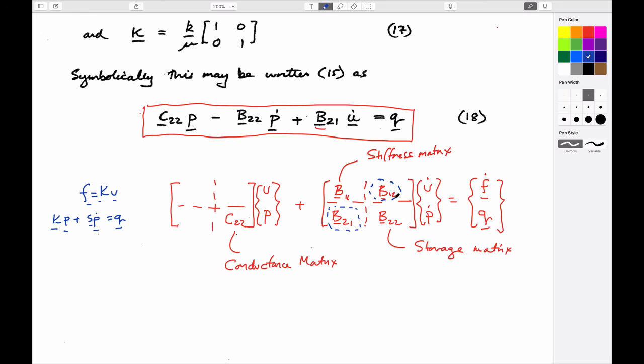And you can define a seepage force, if you write it in a different way. Seepage force is equal to a change in fluid pressure with location. And you can convince yourself that that's the case because a fluid pressure has to be written in terms of newtons per meter squared.